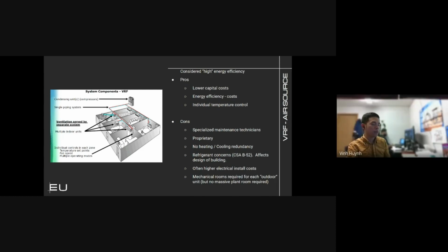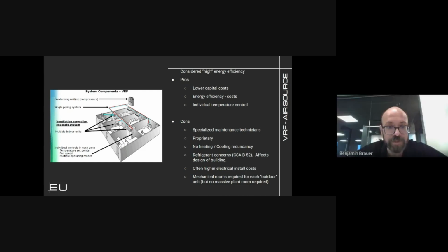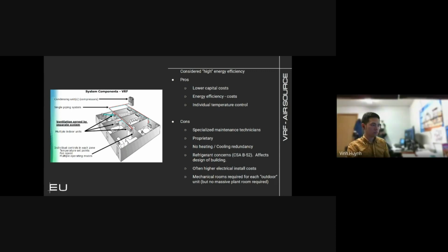That's pretty cool. But what about ventilation? Does it actually do ventilation, or do you have a separate system for ventilation? No, ventilation's a separate system utilizing the makeup air units or air handling units that still have to be there to provide fresh air to the back of these fan coils. A VRF fan coil is just a refrigeration version of the hydronic fan coil. They both require ventilation, a small duct providing fresh air to the back of the unit. Got it. Thank you.